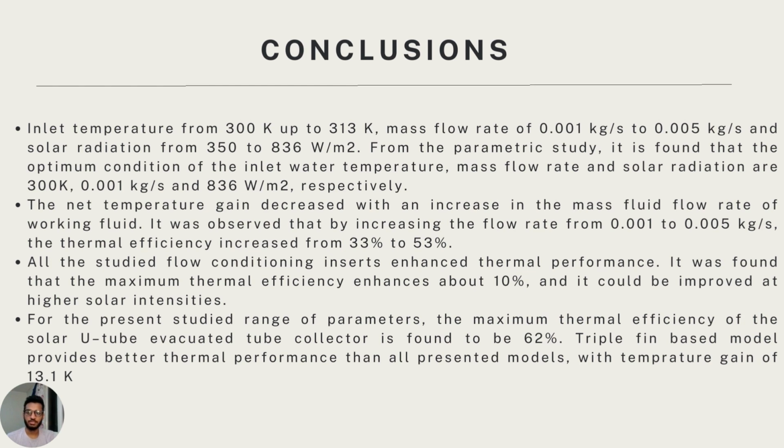The net temperature gain decreased with an increase in the mass flow rate of the working fluid. It was observed that by increasing the flow rate from 0.001 to 0.005 kilogram per second, the thermal efficiency increased from 33% to 53%. All the studied flow conditioning inserts enhanced thermal performance. It was found that the maximum thermal efficiency enhanced by about 10%, and it could be improved at higher solar intensities.